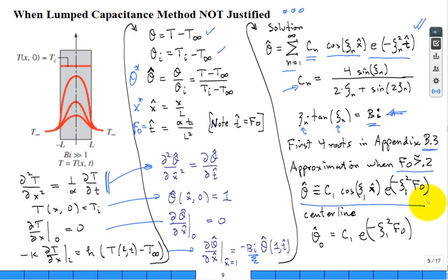But anyway, it all boils down to just the first term when the Fourier number is greater than about 0.2. Now, you think on a time-limited exam, the professor is going to give you something where you would have to sum even the first 4 terms of that series solution? So if you're going to use this equation on a time-limited exam, it's like 99.9% of the time the Fourier number is beyond 0.2, one term.